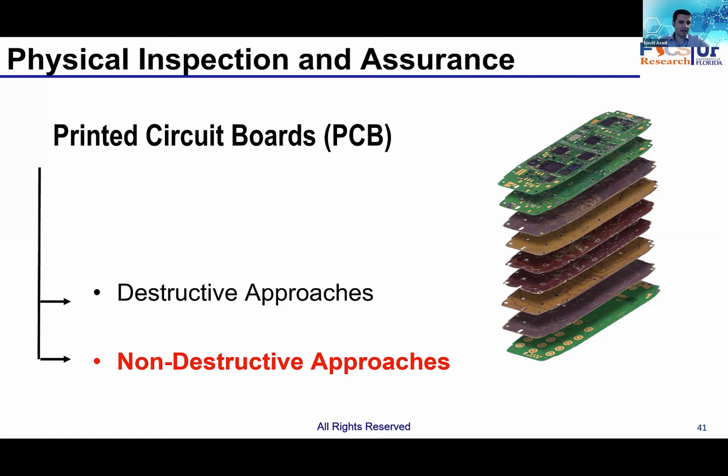But as we go to 7 nanometer, as we go to smaller nodes, your attack approaches are going to be different. And I don't have a slide on it, unfortunately, here. But the same approach that can be done with optical can be done with electron probing as well. It's not going to be contactless. Obviously, you have to do more sample preparation. But because we are talking about FinFETs, with an advanced sample prep approach, you can basically prepare your chip down to the fins, but still your chip is active. So the passive voltage contrast will help to basically collect images and read them the way they are charged or discharged. But it's work in progress. That's actually a very niche area we are working on right now.